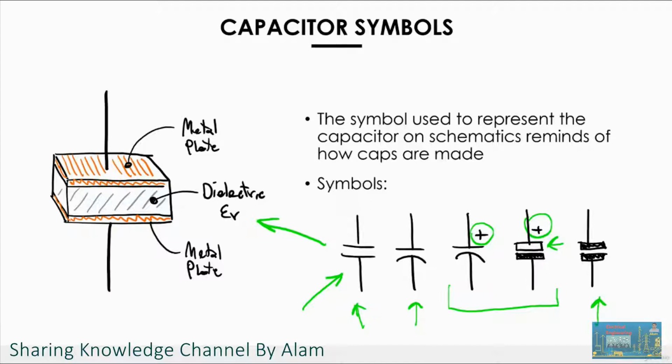is fabricated is such that the voltage at this terminal always needs to be higher than the voltage at the other terminal. So when you eventually put it in your circuit, you have to make sure that the voltage in your circuit is always applied in this direction, and never applied with the opposite orientation. So the terminal on the top in this drawing always has to have a higher potential than the one at the bottom. Otherwise, the capacitor could actually explode. It will definitely be damaged. These components are called polarized.